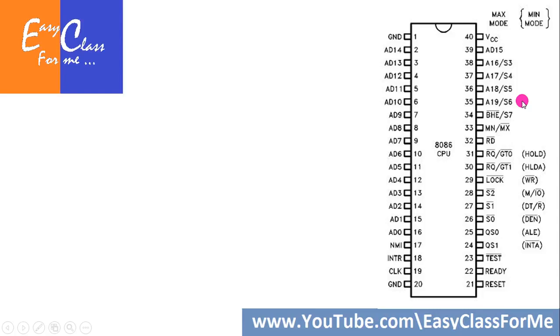To store the address that has been given on the address bus, we have something called address latch enable. Address latch enable is a pin which will be set to a high value when an external device, called a latch, which is also a form of register, takes the address given by the address buses into itself and stores it for future use, because this microprocessor is employed in a system.